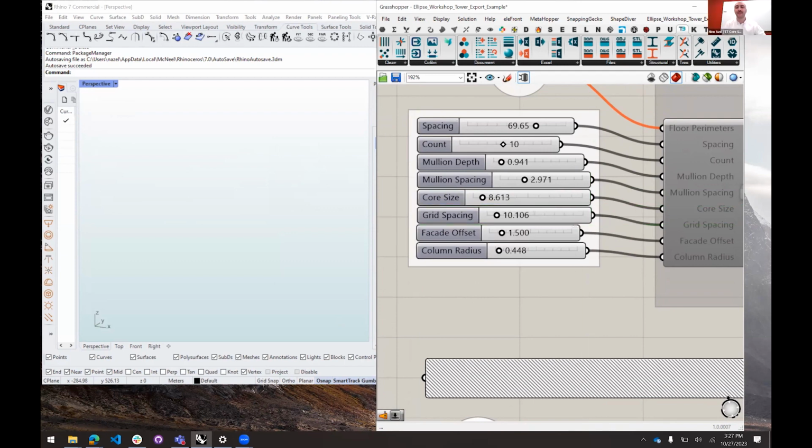But just keep in mind, anytime you see a number like this in Grasshopper and you're using it for any kind of dimension, it's using whatever dimensions Rhino is using. So if you run it in meters and I run it in feet, they're proportionally going to look exactly the same, but one will be much bigger than the other.